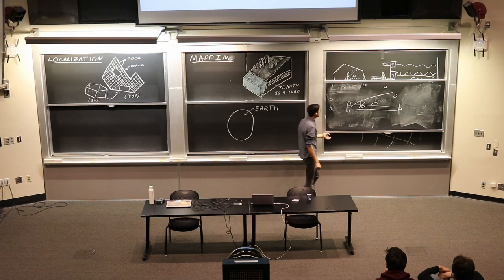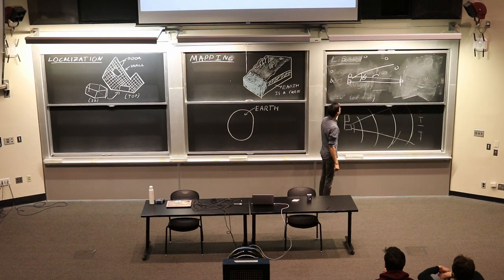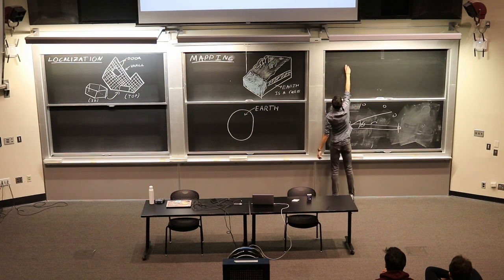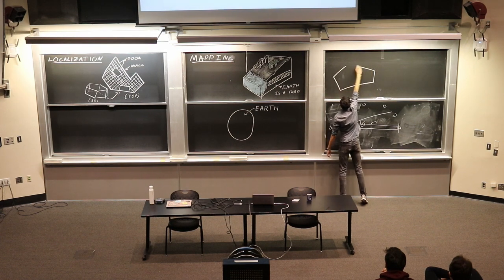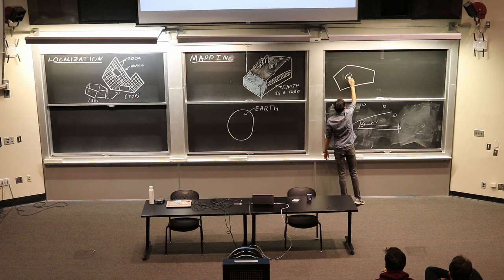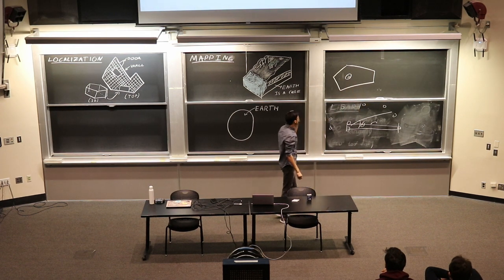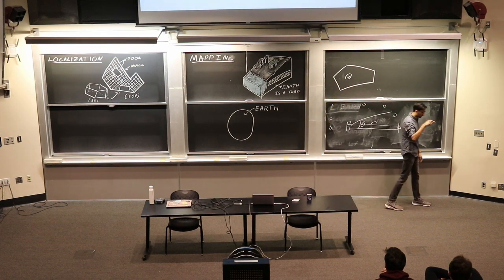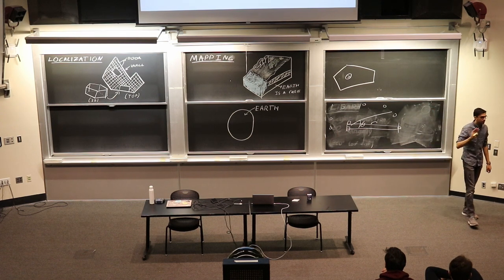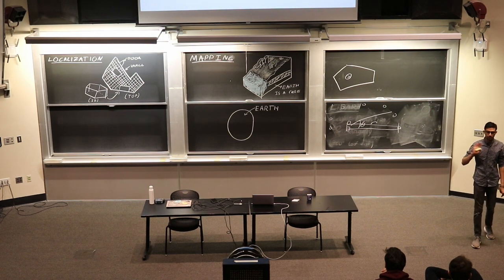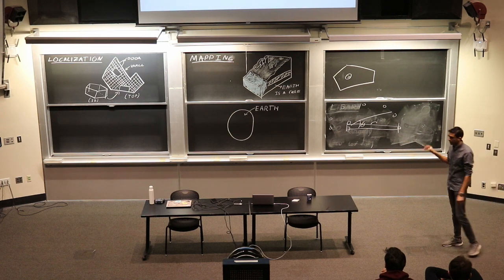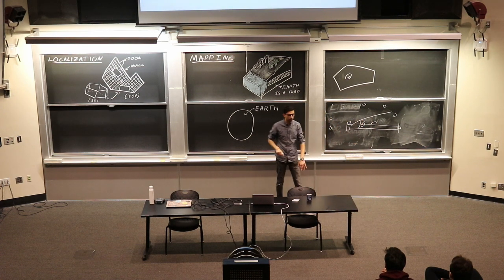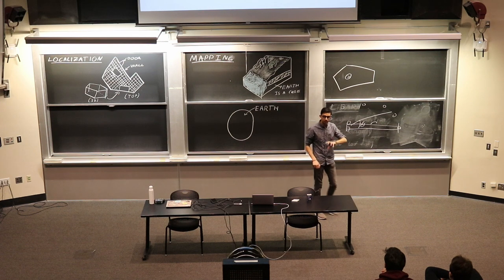So what this means is, let's say, I'm running out of whiteboards. Let's say I have a room that looks like this. I put a LiDAR here, and that's the front of my LiDAR. The first thing that happens is this LiDAR is going to spin around, measure its points, and send all of this through a binary stream to your computer. You don't need to worry about the binary stream because all of the LiDAR drivers that come with the LiDAR take this binary stream and convert it into something usable. This usable thing it converts it into is called a point cloud.